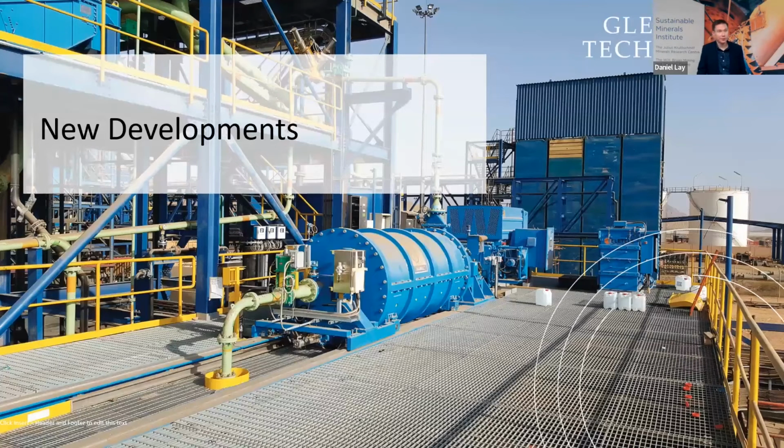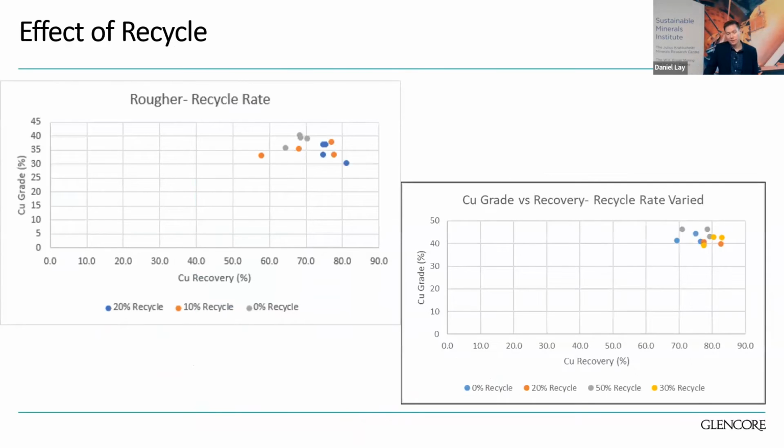So looking at some new developments, some of the work that we're busy with extending our research. This is a few slides showing the effect of recycle. It has been a bit of a debate with the Jameson cell. The Jameson cell incorporates the recycle for the purposes of process control rather than for metallurgical reasons. And we've been doing some test work to prove this. So we've been varying the recycle between 0 and 50%.